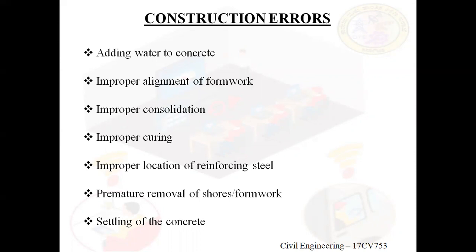Next, improper curing. We know curing is very important in the construction field. If we do improper curing, shrinkage cracks will develop automatically. The cracks will develop, that may be plastic shrinkage and ultimately other types of shrinkage cracks will also develop, which affects the serviceability and durability.